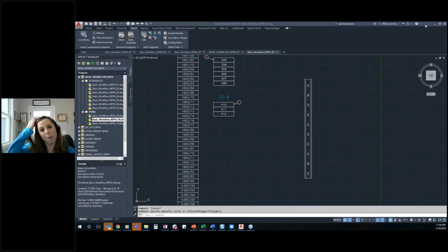I get a lot of questions around dynamic blocks being supported in electrical, and there's a lot of feelings out there that they're not. And that really comes down to the swap update block utility, because in many ways what happens in the background of a dynamic block is that if it's been dynamically switched to something else, that can sometimes change the block name. So if you're doing a project-wide search and a swap, you will hear from some people that you don't get dynamic block support in that sense. Outside of that potentially happening, and that all depends on how you're building your dynamic blocks, there's really no reason you can't utilize dynamic blocks inside of AutoCAD Electrical. So just a little tip from me to all of you on that one.